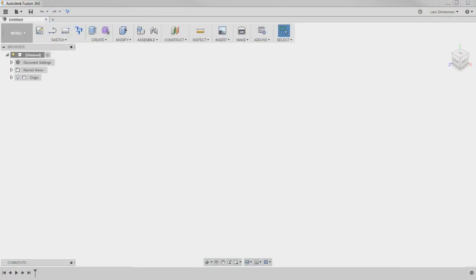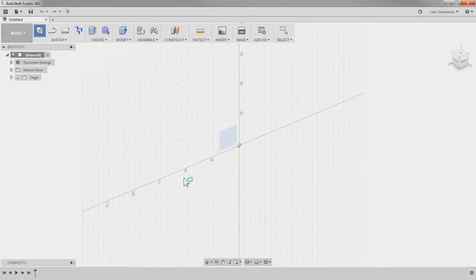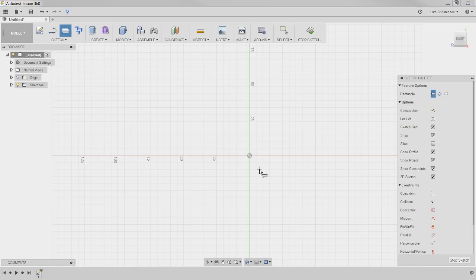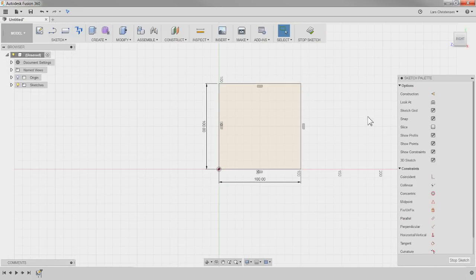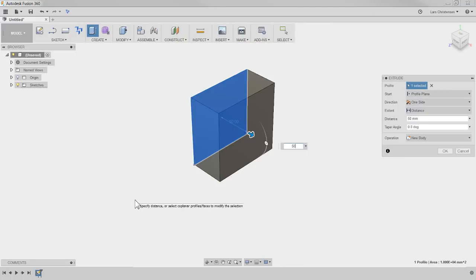Let's not waste it. Let's get in and see what some of my screw-ups were starting out. So, find the button here and you should see Fusion 360. All right, so I'm just gonna start out here from scratch and start a new sketch. And I'm just gonna select one of the planes here and start a corner rectangle and give it a couple of dimensions, 100 millimeters, hit the tab key, by 100 millimeters, just like this, and hit Q for press pull, and I'll make it 50 millimeters thick right here.